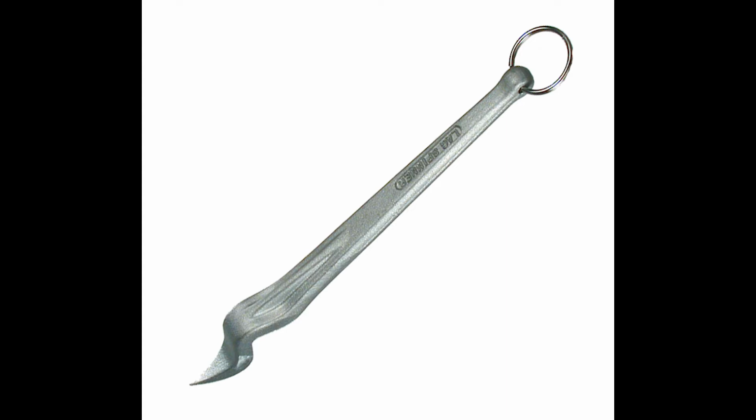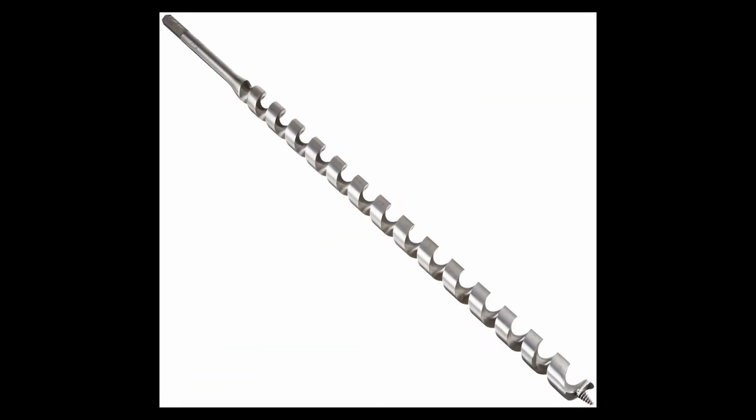Since cords can be an issue, gasoline-powered drills are generally preferred, but cordless drills can, in some cases, have enough torque to drill through the limb. Regardless of drill type, a ship auger bit should be used in tree support applications. Just make sure it's sharp.